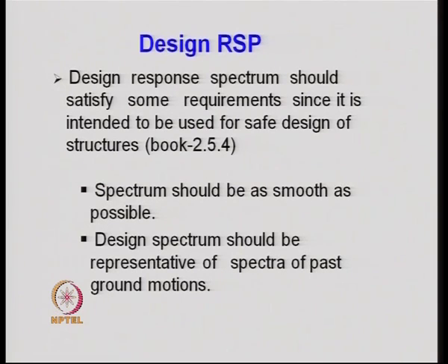Now, let us come to the design response spectrum. The design response spectrum is the response spectrum which is used for designing all the structures for future earthquakes which are not known. Therefore, it is a difficult task. What generally is done for obtaining the quantities for a future earthquake is that we try to see the trend of the parameter that we are looking for in the previous earthquakes.